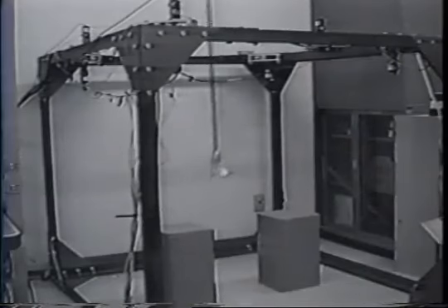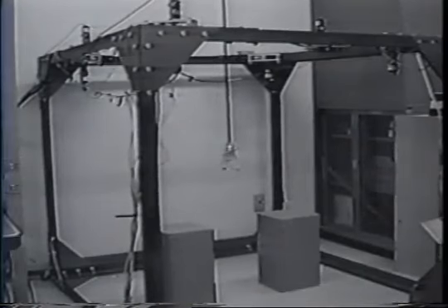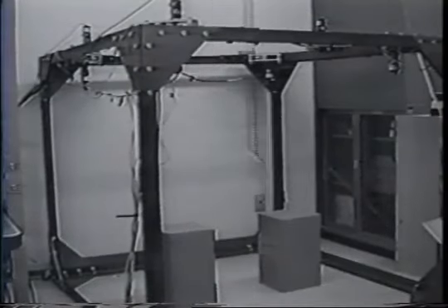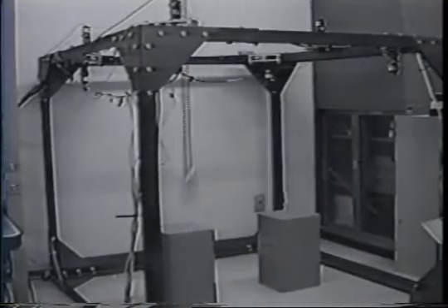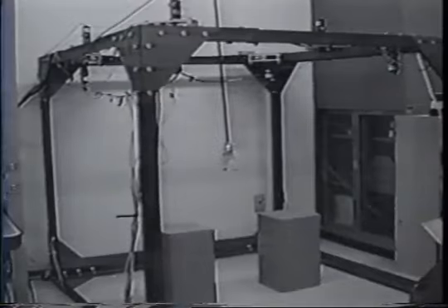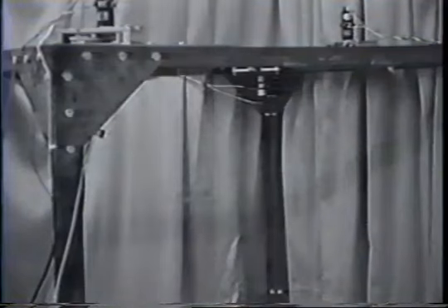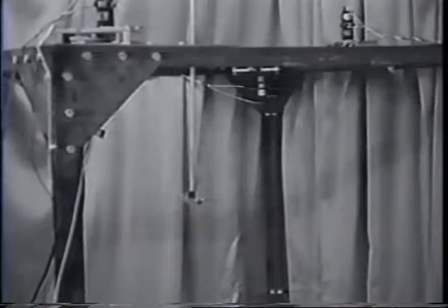In high-speed motions, vibration comes up as a crucial problem. To eliminate vibration, internal force which is generated by redundant actuation is effectively utilized. As a result, vibration does not occur in high-speed motion of the proposed robot. Even if the servo motors have 60 watts capacity, the peak acceleration achieves over 100 G and maximum velocity achieves 13 meters per second.